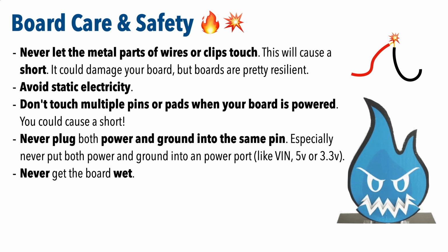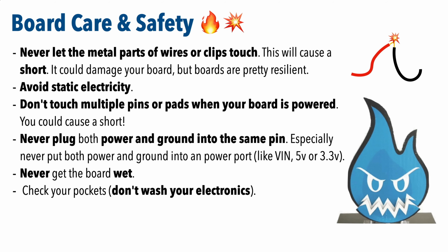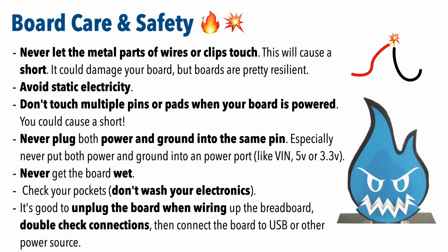Never get your boards wet. I don't recommend that you carry your electronics around in your pockets too, but always check your pockets before you do the wash. And it's definitely a good idea to unplug your board from USB or power when you're doing wiring, double check your breadboard connections, and then plug things back in. Now don't be afraid to work with electronics, but definitely keep these tips in mind and pay close attention when wiring things up.